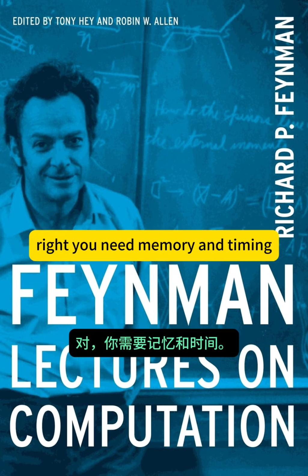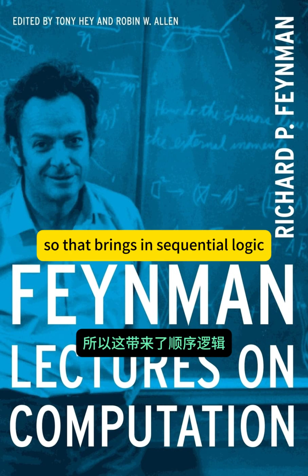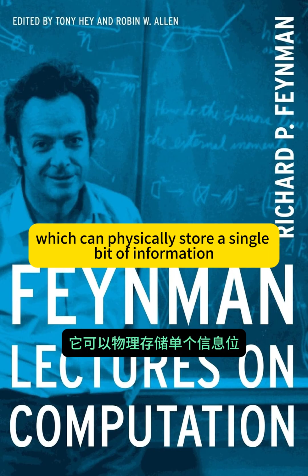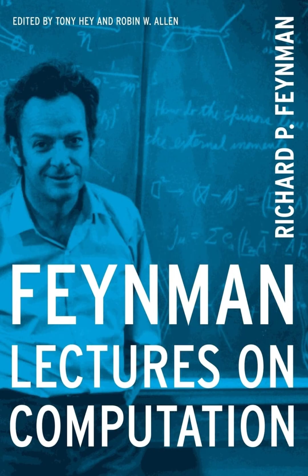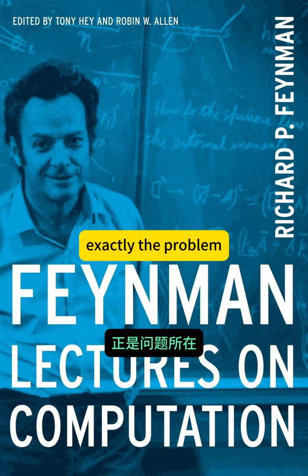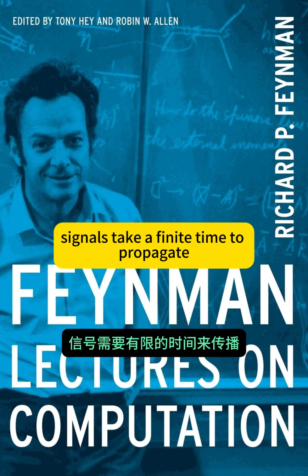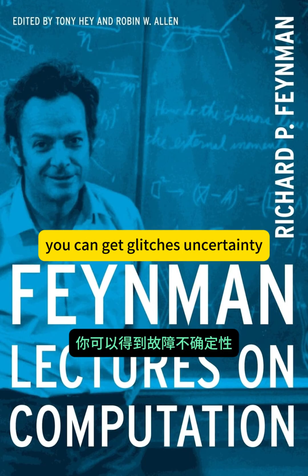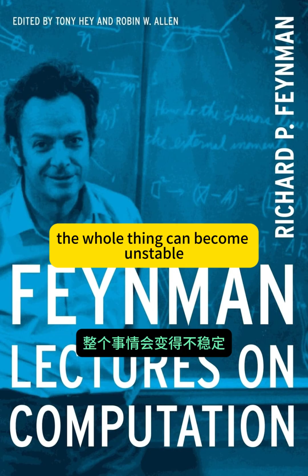Right. You need memory and timing. So that brings in sequential logic. You have elements like the RS flip-flop, which can physically store a single bit of information. It remembers. But timing's tricky, isn't it? Signals don't travel instantly. Exactly the problem. Signals take a finite time to propagate through wires and gates. If inputs to a gate arrive at slightly different times or change too quickly, you can get glitches, uncertainty, and the whole thing can become unstable.